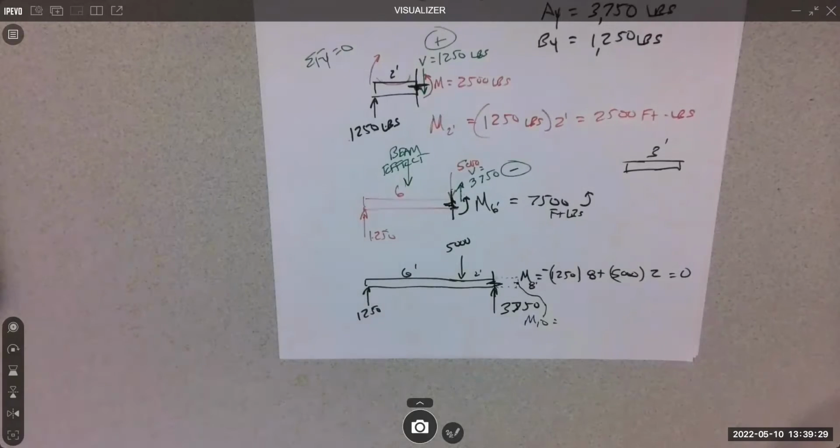Essentially shear stress and shear failure is saying, we have a beam and it looks like this, but potentially it could do this and just fracture right here, just shear off if that force was great enough and close enough to that support. So it's more likely to break at the support than in the middle under shear, yes. It's more likely to fail in bending in the middle, in the span.